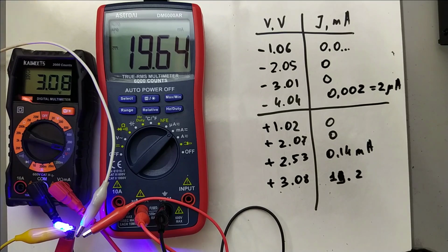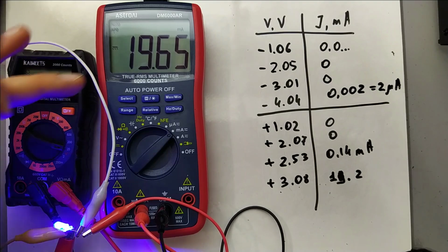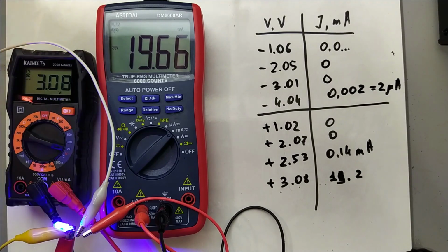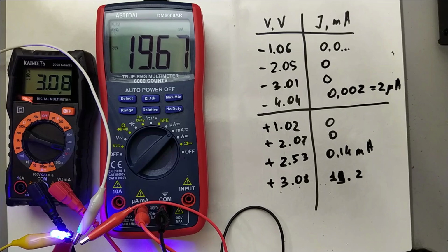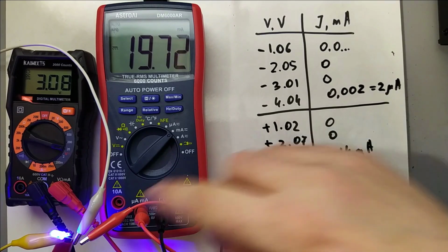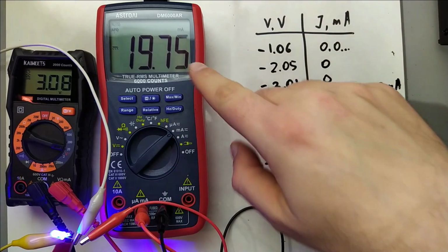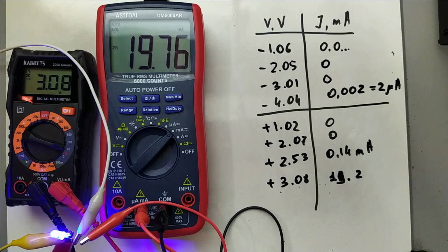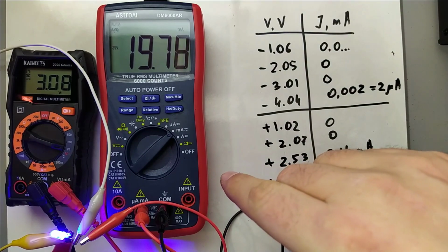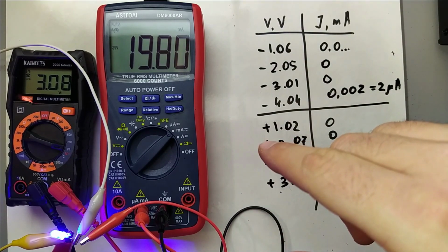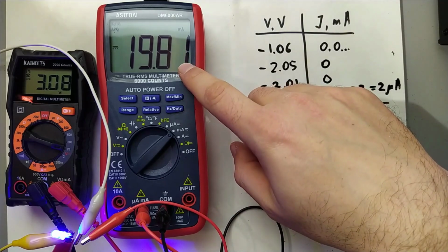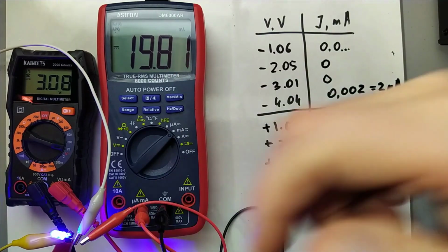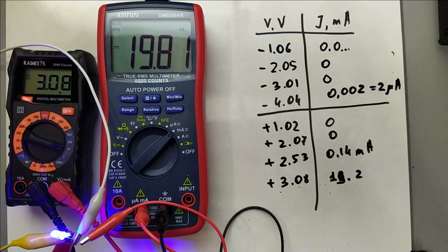So the potential barrier drops at fixed voltage, and we observe some increase in electric current which flows through this LED. Obviously, if we see such thermal effects by increasing current in the LED, we don't want to go to much higher forward bias, because then current will be very high and we will just burn the LED.